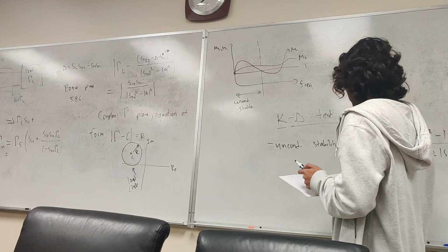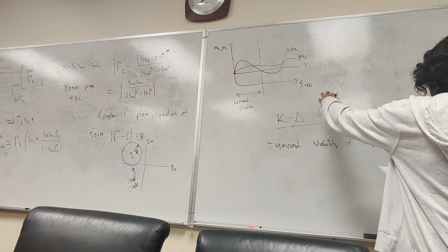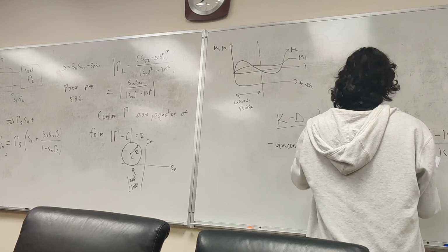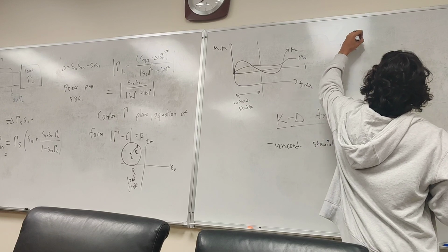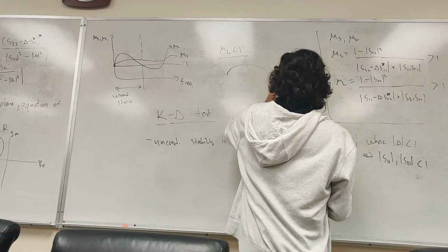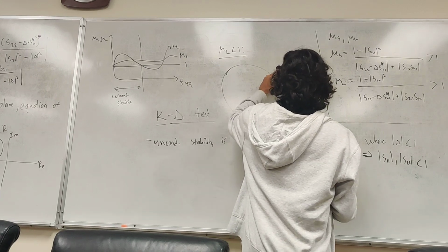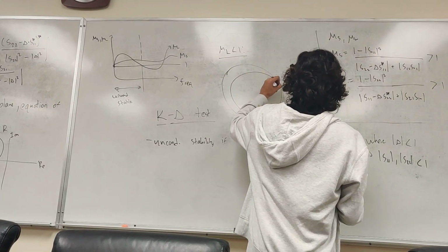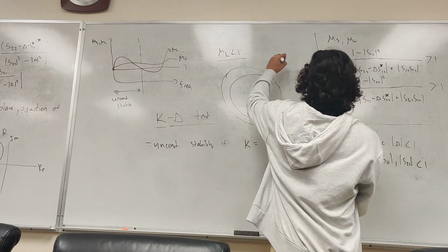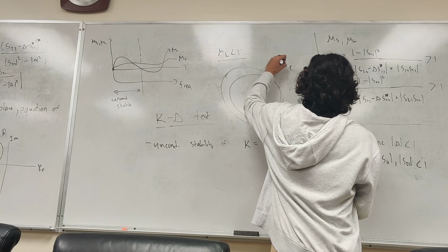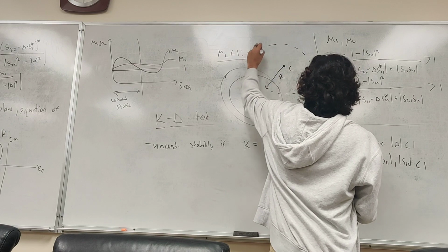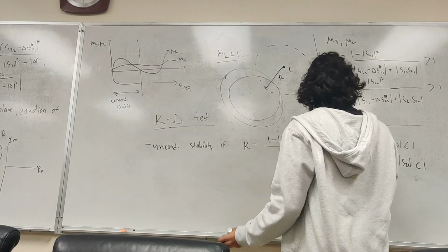Okay. Now I'll give you guys another example here, beyond just this. Let's say we have mu L less than 1, and I'll draw a Smith chart here. Oh, that's not good. Pretend this is a well-drawn Smith chart. This is our Smith chart, and this is our point C. This is our R, and that's our stability circle, the thing we talked about over there.